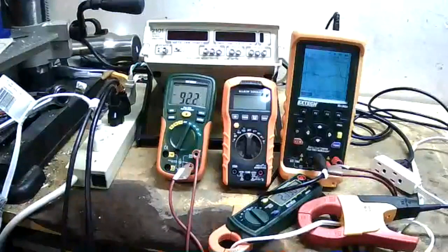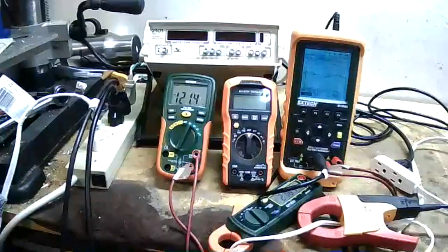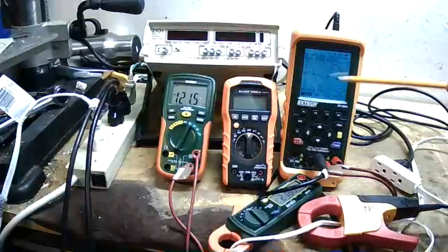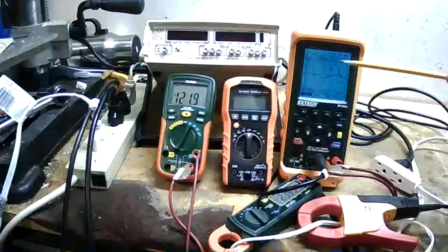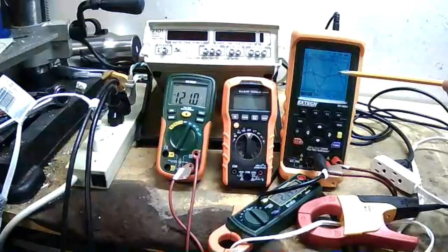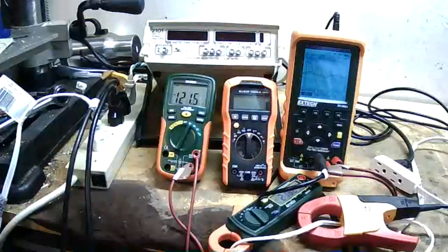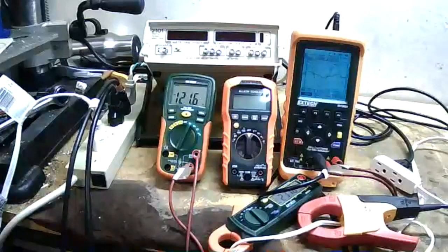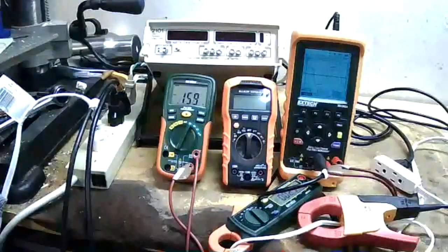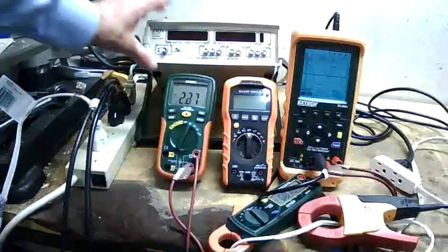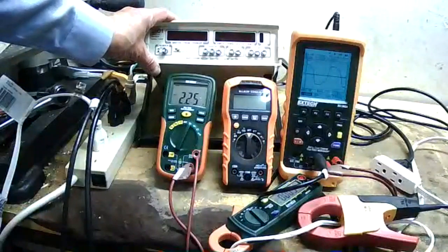Now, we've got the current and the voltage almost in phase, but they are not in phase. If you look closely at this, you can see the peak on the voltage waveform is here. The peak on the current waveform is there. When we talk about power factor, we'll use that and we'll actually calculate power factor. But all I'm going to use it for today is to say no, they are not in phase, because I'm going to measure the power a different way. And the way I'm going to measure the real power is using this device, which is a watt meter.